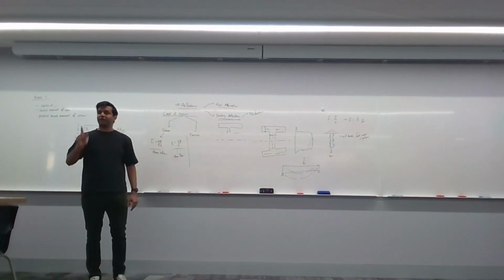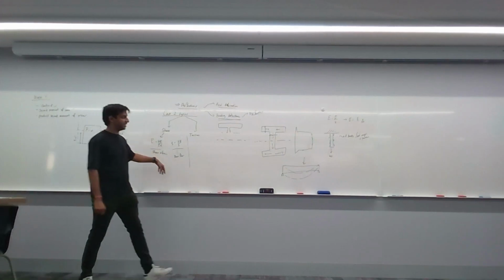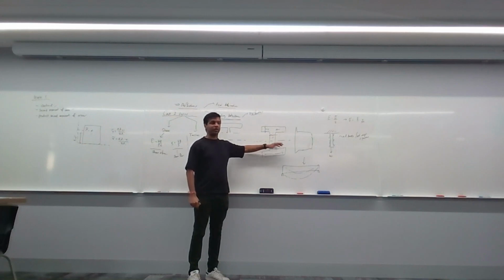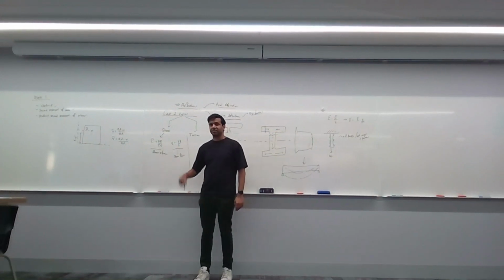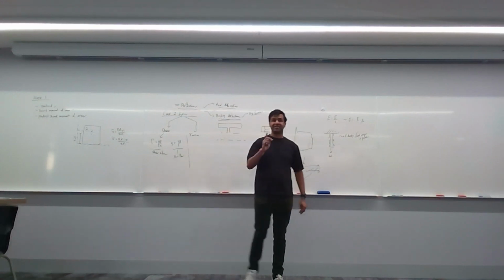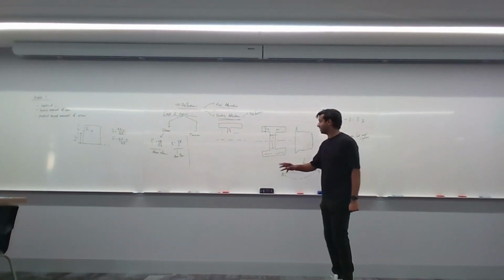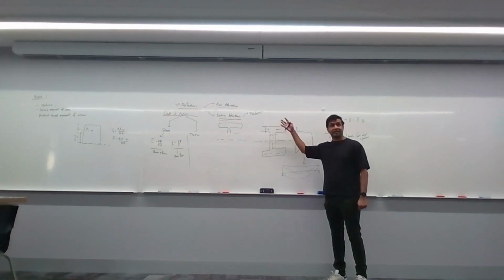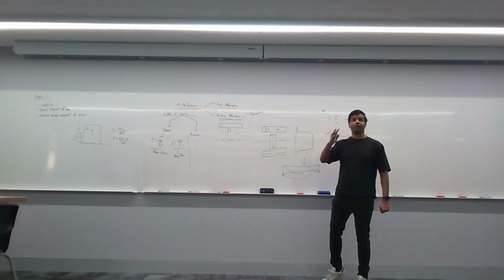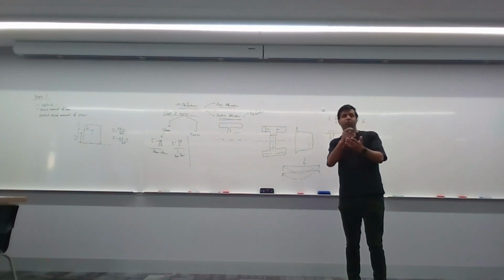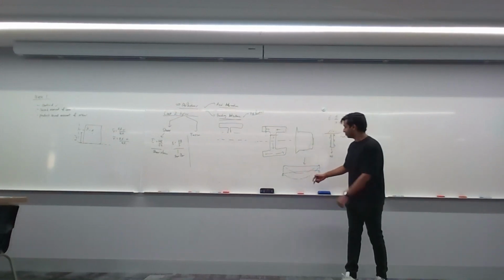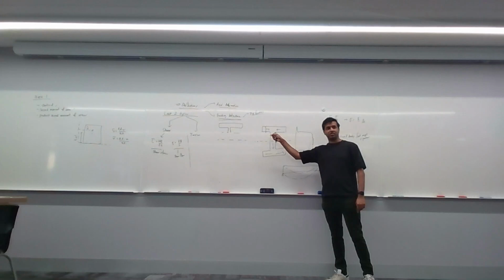If you notice, the direction of VQ over IT is moving up and down across the cross section. We only deal with the cross section for shear stresses. But when we are talking about shear flow, which is VQ over I, you must understand that the direction we're talking about isn't up and down anymore. The direction we're talking about is into the page. That's very, very important. So questions like, how strong does the weld have to be? How many nails do you use to connect this thing and that thing? Those are all related to directions into the page, right?